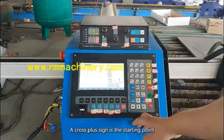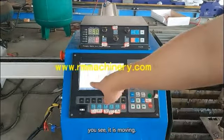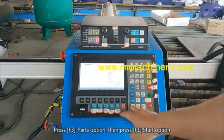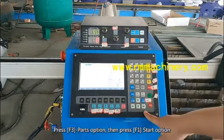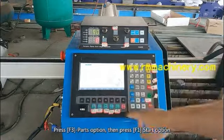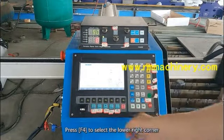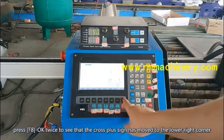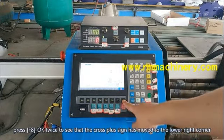The plus sign is the starting point. You see, it is moving. Press F3 Parts option, then press F1 Start option. Press F4 to select the lower right corner. Press F8 OK twice to see that the cross plus sign has moved to the lower right corner.